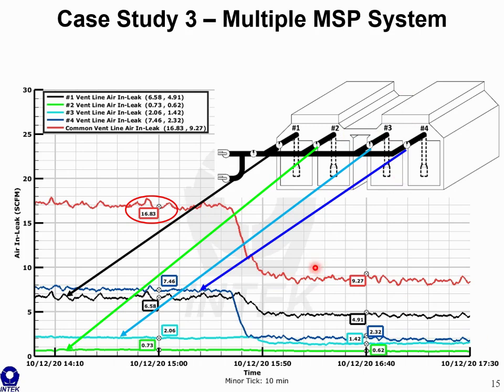So based on this data, we were able to conclude that there likely was very little leakage from turbine steam seals and expansion joints. This meant that the effort searching for leaks could be focused on penetrations in lines entering near the number 1 and number 4 bundles. Narrowing down the leak search area would have been impossible, leading to an arduous search process, without having a probe installed in each of the vent lines.